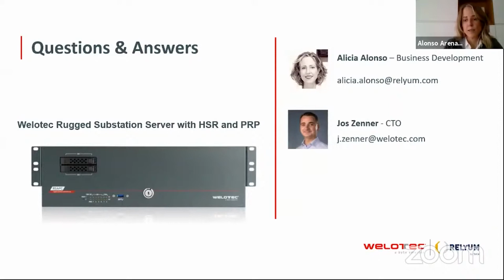And this is why this kind of redundant technology is used, for example, in smart grids. I mentioned the maximum latency of 1000 microseconds. This is based on the standard for a protection reaction that has to be under 3 milliseconds.